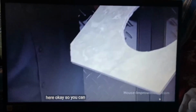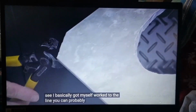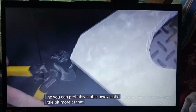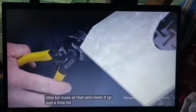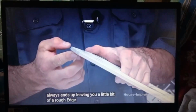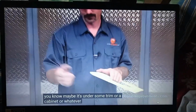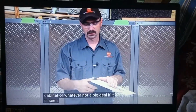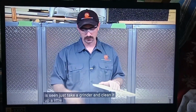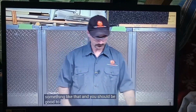Okay, so you can see I basically got myself worked to the line. You can probably nibble away just a little bit more at that. Clean it up just a little bit. It just about always ends up leaving you a little bit of a rough edge. Now if that's not seen, maybe it's under some trim or a cabinet or whatever, not a big deal. If it is seen, just take a grinder and clean it up a little bit, or a filing stone or something like that, and you should be good to go.